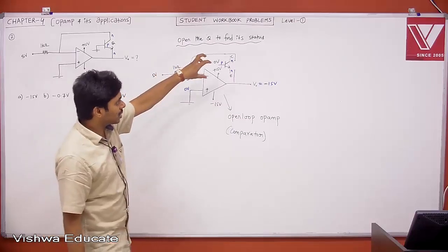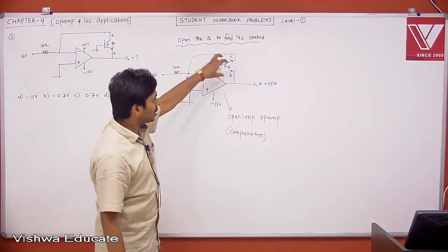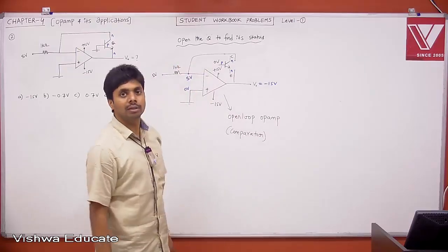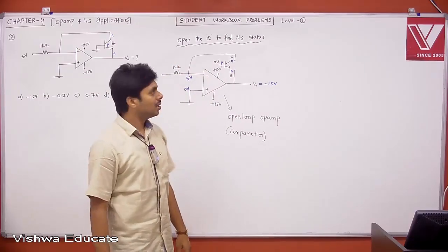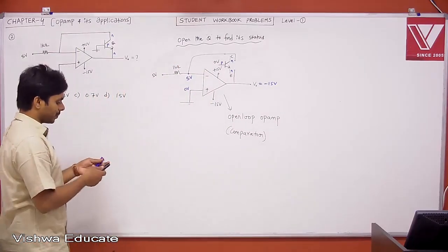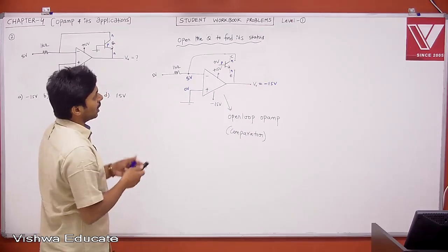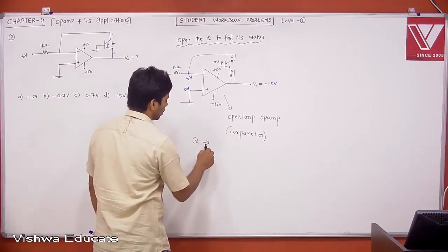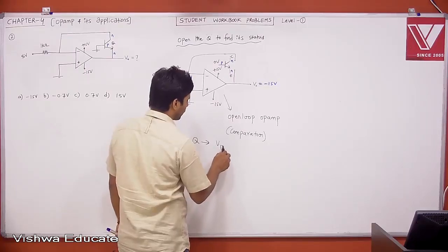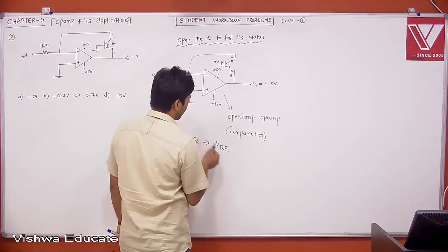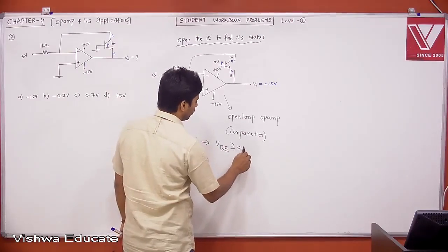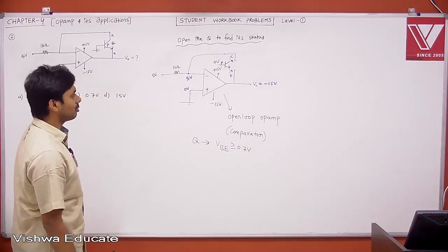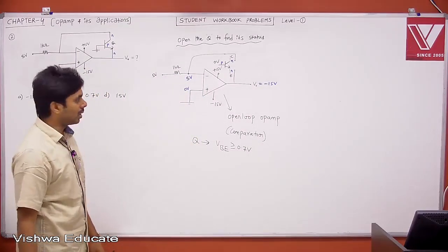Now bring back your transistor. Now connect transistor. When you connect transistor, it is seeing 15 volt across VBE. Yes, it will be on. It will be strongly on, let us say. Then what you get immediately, but how much it needs, it will take. Therefore, your transistor Q is having VBE greater than or equal to 0.7. Therefore, it will conduct. Therefore, your transistor will be on, then virtual ground concept is valid, right?